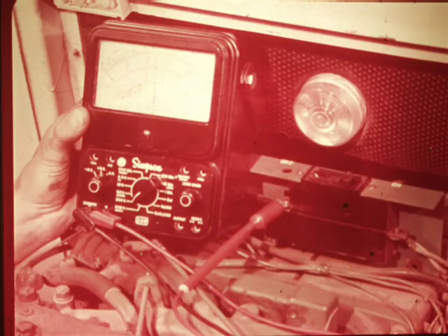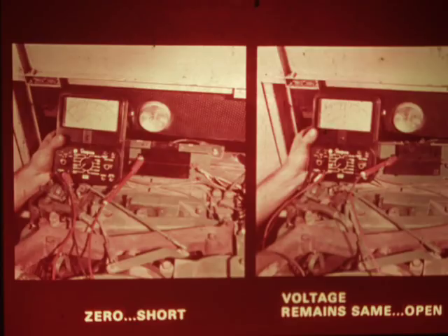Start the motor generator. Then check with a 110-volt test light or an AC voltmeter, with one lead connected to ground and the other to the breaker terminal. If there is power at this spot, the trouble is an open or short circuit in the wiring somewhere. To determine which, close the breaker. If the voltmeter reading then goes to 0, there is a short in the motorhome's wiring. If the reading remains the same, there is an open.